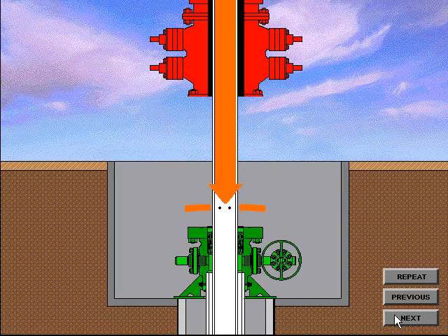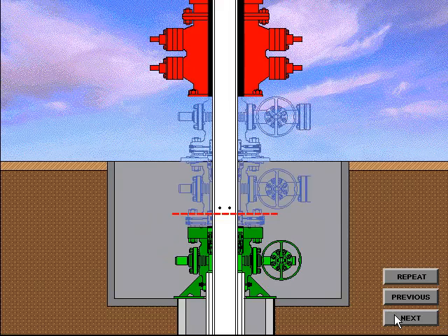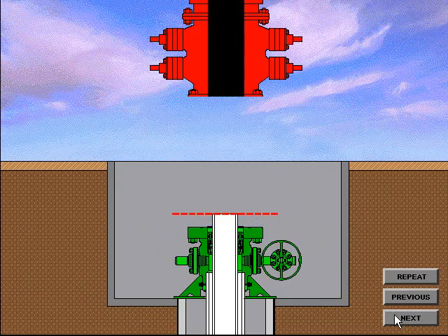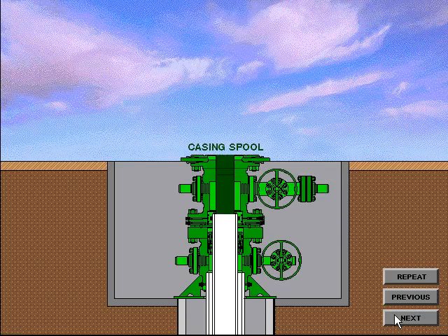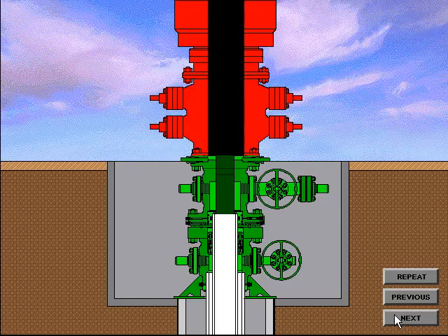Holes are cut in the casing to allow the drilling fluids to drain out of the casing riser. When the casing has drained, a rough cut is made and the balance of the casing riser is removed. The BOP system is removed. The casing spool with a crossover seal is installed. The BOP system is nippled up and preparation is made to drill out for the production casing string.